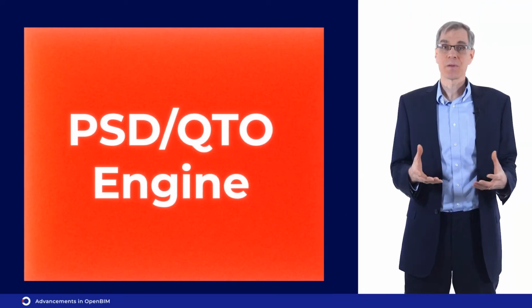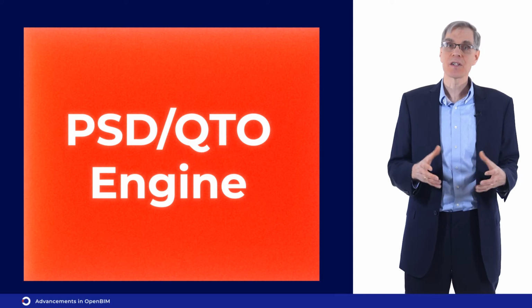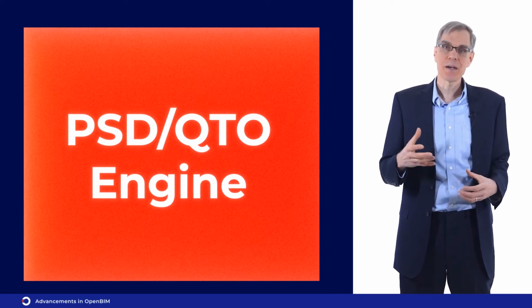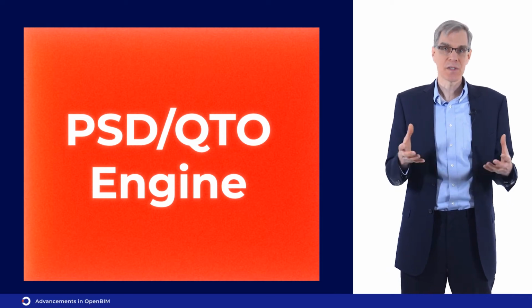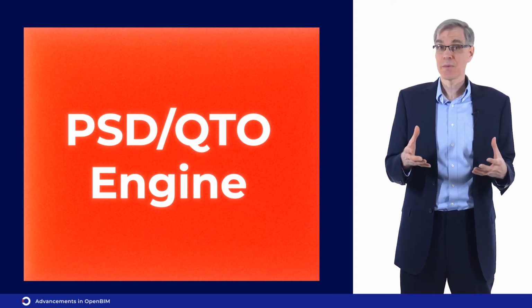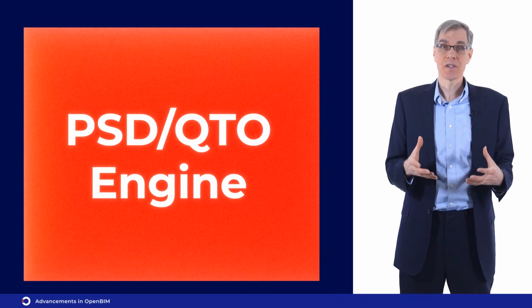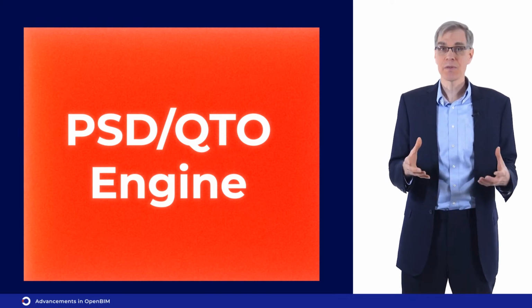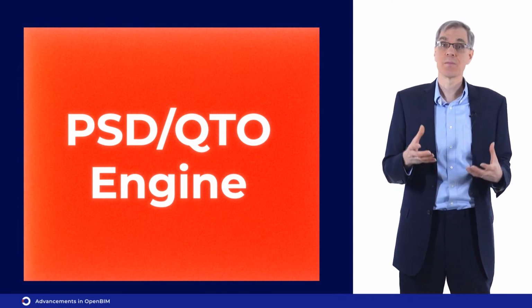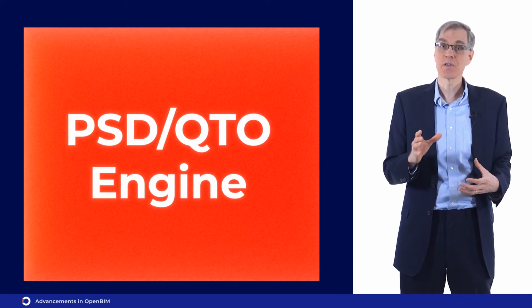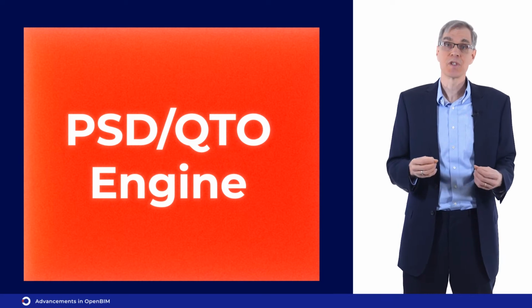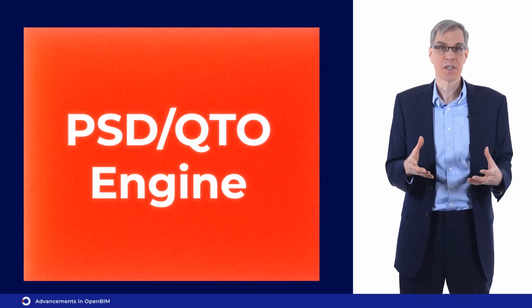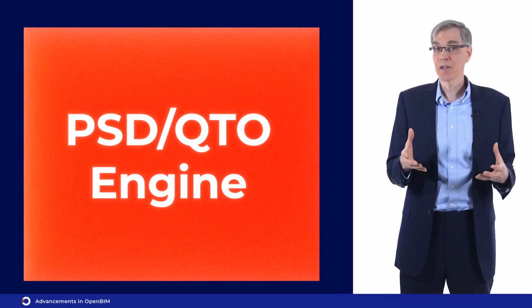Another interesting client request is for an automatic or semi-automatic method for populating property and quantity sets within an IFC model. To address this issue, we will be developing a new PSD QTO engine to facilitate the creation of property sets and quantity takeoffs from XML-based PSD QTO definitions. Finally, we can now read IFC JSON, which is a text-based encoding of IFC based on JSON, a common standard for transmitting data in web applications.